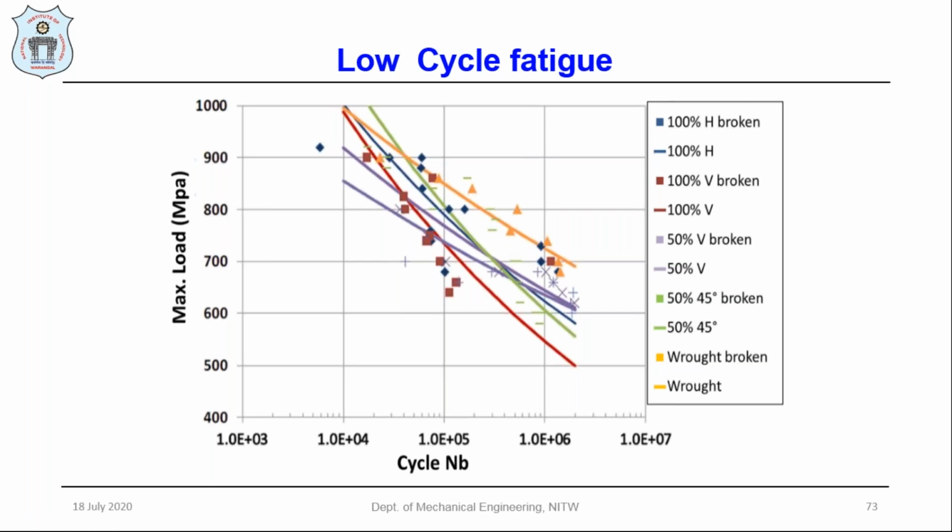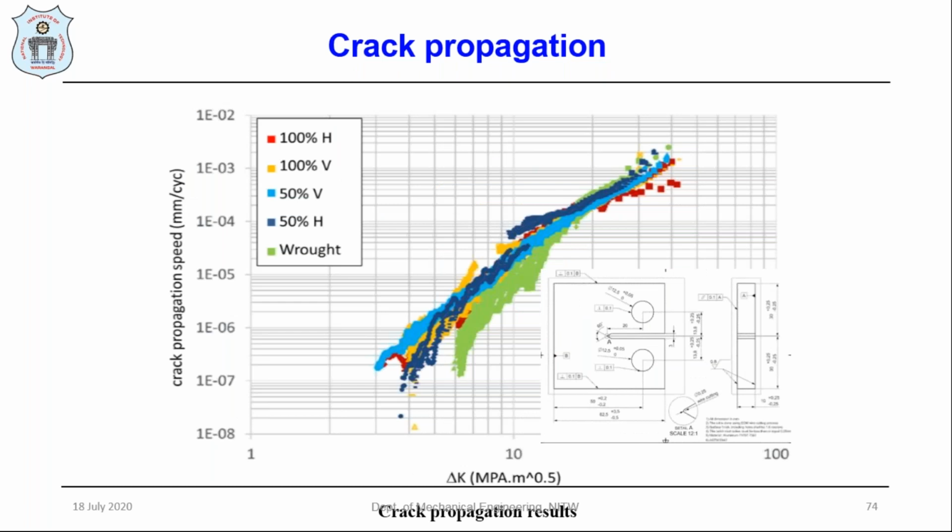The fatigue properties are almost matching the wrought alloys, and the crack propagation is also almost matching the wrought alloys, with respect to all the sample extractions from the fabricated components.